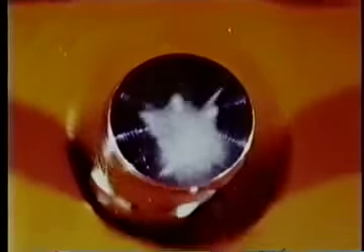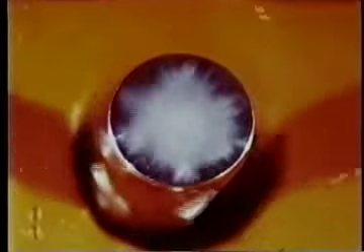The total amplitude of vertical oscillation is only 0.02 of an inch, but the pressure is changed from below vapor pressure, as the button is accelerating upward, to a high pressure, as it is accelerating downward, at the rate of 14,000 cycles per second. After 1 minute, the highly polished surface has been eroded, and significant weight loss has already occurred. Here is a side view of this experiment.